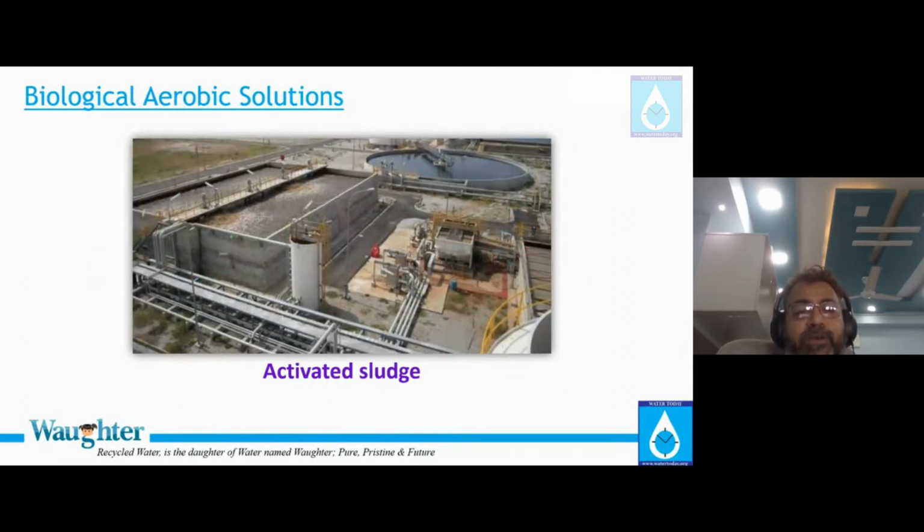Now, getting into detail, the activated sludge process is a process where we will have all the heterotrophs, autotrophs, everything living happily in the system. We will have aeration equipment where they will grow. We will have a separation equipment here, which is a clarifier. The sludge will come out from the bottom, which will be sent to my anoxic tank. This is the anoxic tank where we will have some kind of denitrification, and from here the feed will go back. Excess sludge will go into the sludge thickener area. From the thickener area, it will be pumped towards the centrifuges to make the sludge cake. So this is a typical activated sludge diagram.